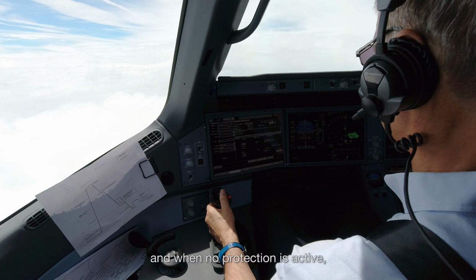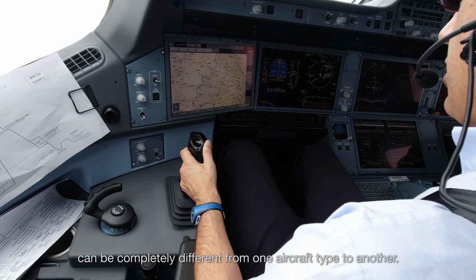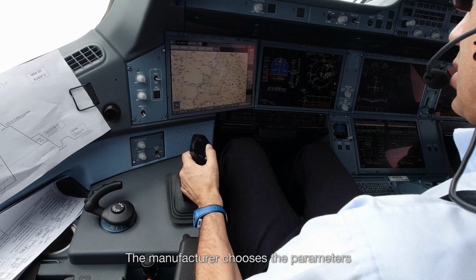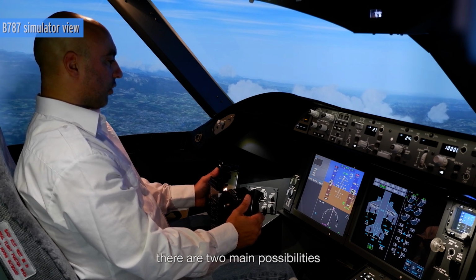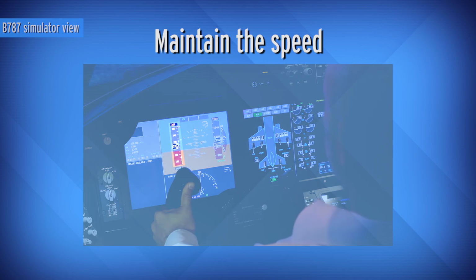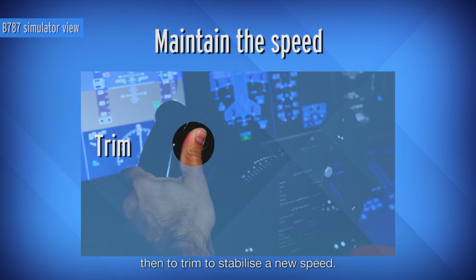Without any failure and when no protection is active, the aircraft is in normal law. However, normal law can be completely different from one aircraft type to another. The manufacturer chooses the parameters that are controlled by the stick or the control wheel. For pitch in normal law, there are 2 main possibilities when in level flight. Maintain the speed. The aircraft has a positive static stability. When accelerating, it is necessary to push on the stick or on the control wheel, then to trim to stabilize a new speed.